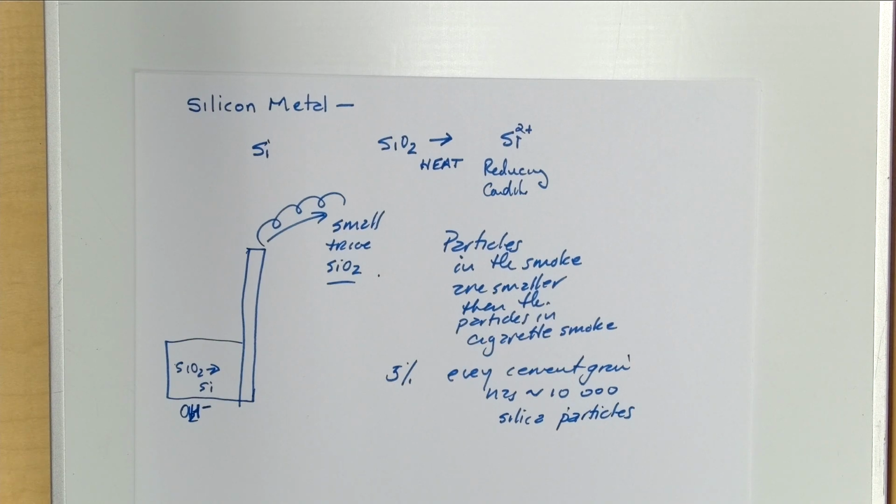And so once you get at about 5%, the cement particles aren't in charge anymore. Now it's silica fume. Remember we showed you the aggregate where it's just full and we could pour sand and we could pour water in still. That same thing happens at the cement scale. The silica fume really densifies that concrete. Amazing densification.